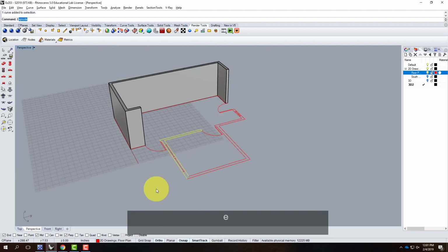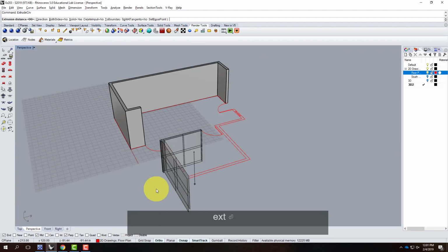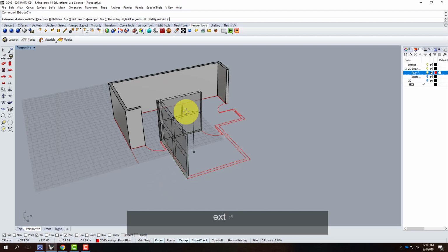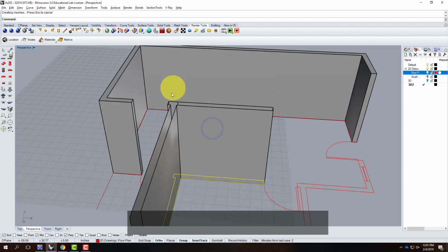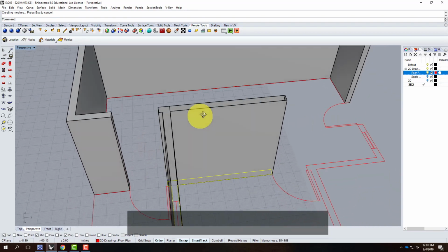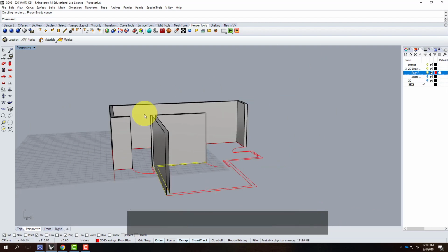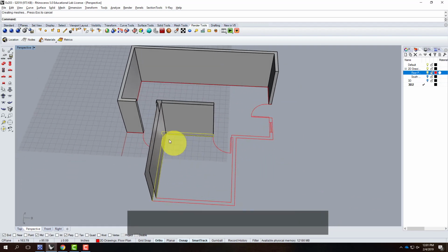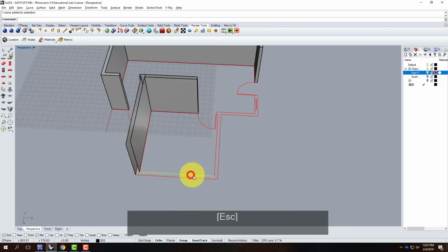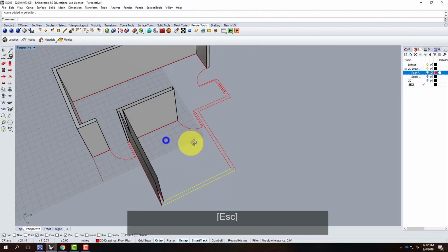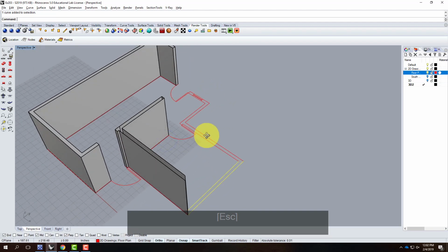But when I went and did the extrude curve, and I went to try to do that extrusion, I can have solid set to yes, and I could snap to right there. But you see it's not making this object solid because it's not a closed curve. So that presents problems down the road because you're going to have to come back and also extrude these other pieces. They're not all going to be part of the same closed polysurface, so it's going to get complicated.